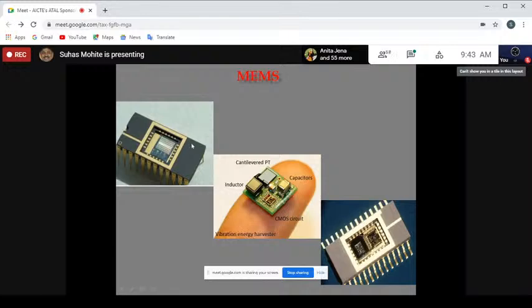but immediately the electronics is sitting next to it, and therefore these devices are in some sense protected from the noise in the environment, because there is not a big gap between the sensor where the tiny signal is produced and the electronic circuits which carry out the immediate signal processing, such as amplification, filtering, and similar processes on the signal processing circuits that are built in the vicinity with various kinds of operational amplifiers and devices. Then the sample and hold and all those circuits will be sitting pretty close to the transducer, and therefore there is little loss of signal, and little scope for noise to play a role there.